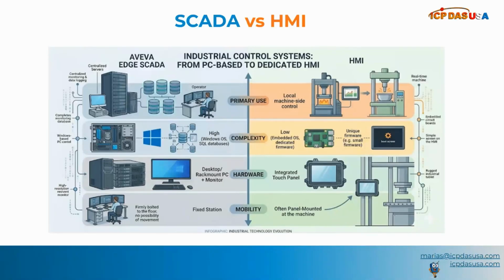At the field level, sensors provide that critical 4 to 20 milliamp signal, and the M7017 Modbus RTU based analog input module digitizes those signals into Modbus RTU communication, and it puts the data into Modbus registers for easy access from other equipment. The PLC implements the logic, manages the machine's operations, and communicates over RS485. Instead of pushing data across the entire plant network to a SCADA server, in local HMI systems, the PLC connects directly to the HMI via local Ethernet or serial link for instant visualization.